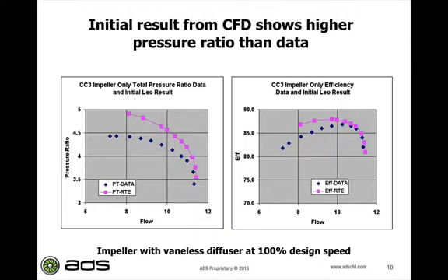The range is smaller. So I believe many people will encounter a similar problem at the very beginning of the first simulation: why the calculations are so different from the experimental data. So we went through many root causes and asked ourselves, is the turbulence level right? Is the surface roughness right? Is there geometry we missed? Is there a boundary condition we did not put in right?